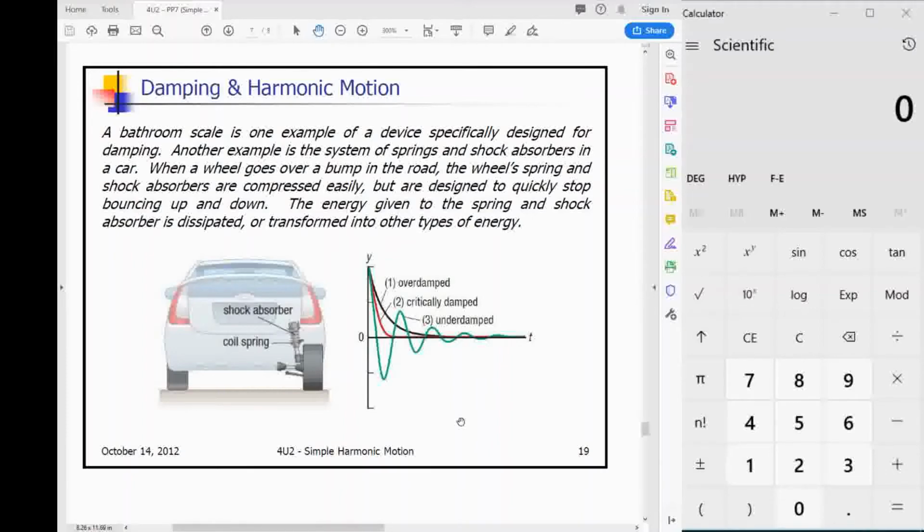And the undershoot for an underdamped system is important as well, because if that undershoot goes past the 3 volts, for example, it might start to alternate the signal from a 0 to a 1 back to a 0, whereas we wanted it to go from 0 to 1 and stay at that 1.